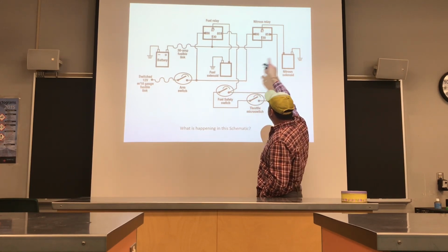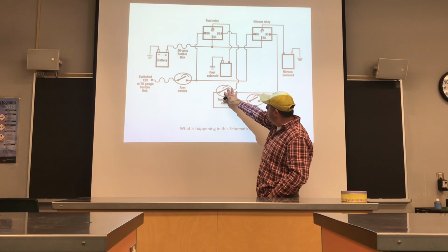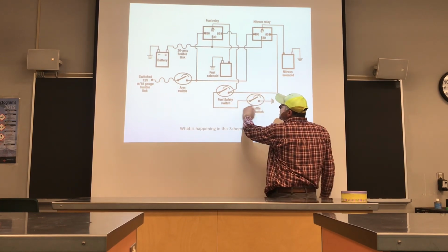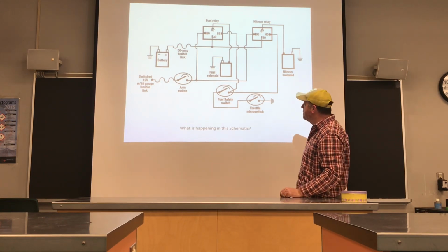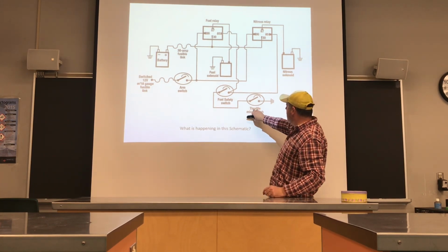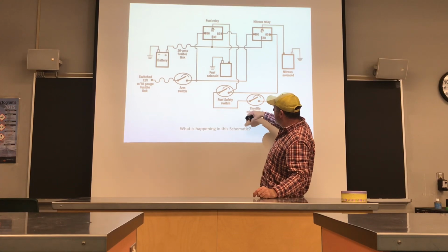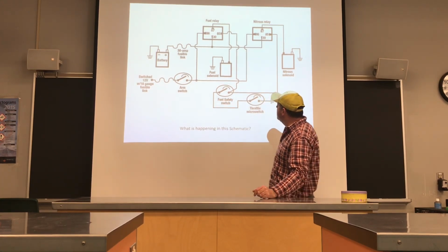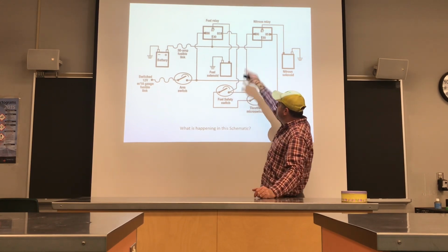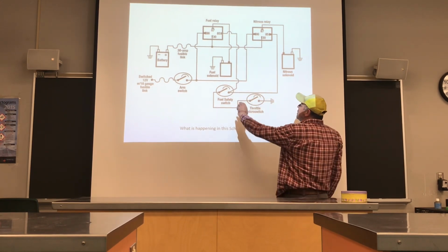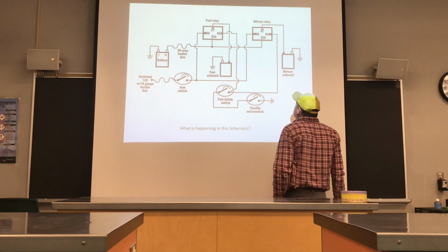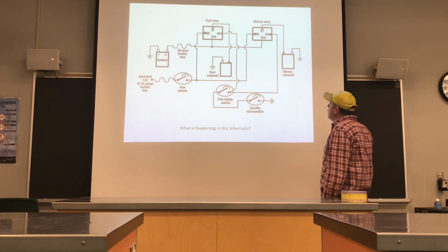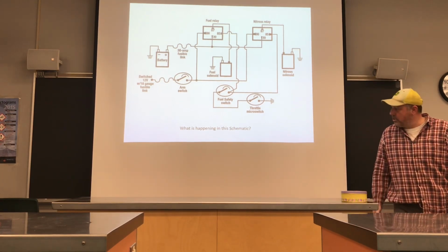So pin 85 on each. We're basically controlling what happens from the ground side this time as opposed to the positive side. So when we use our throttle micro switch, say we throttle it up and we close our fuel safety switch, it completes the ground to the relay, which allows power to flow to our fuel on solenoid or off solenoid and to our nitric solenoid.